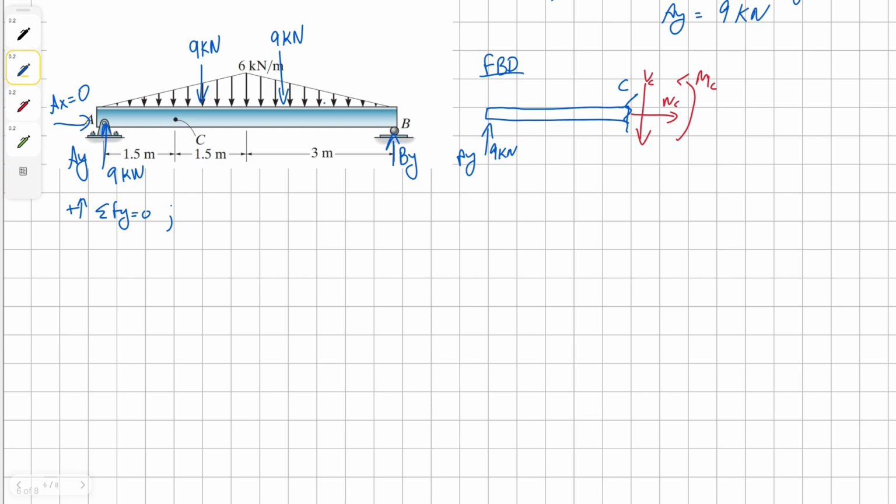And before we do that, we'll have to determine our point load on this beam from the triangular distributed load we had earlier. So first of all, we need to find the uniform distributed load value, which is simply going to be, we're going to use proportionality.